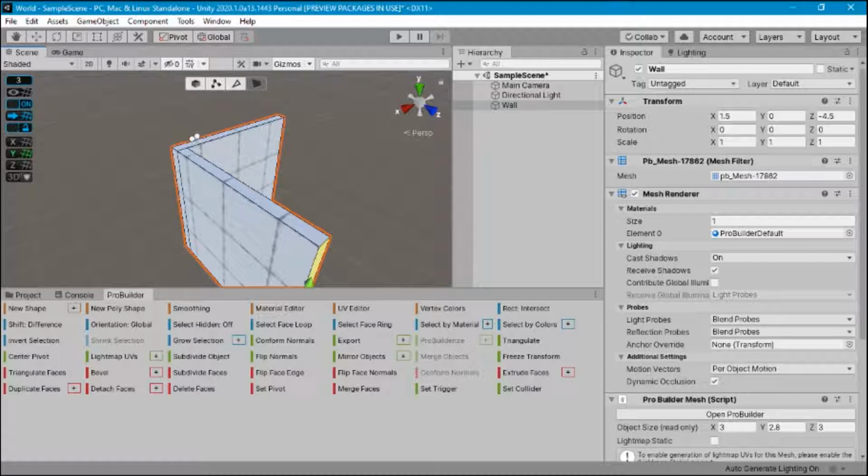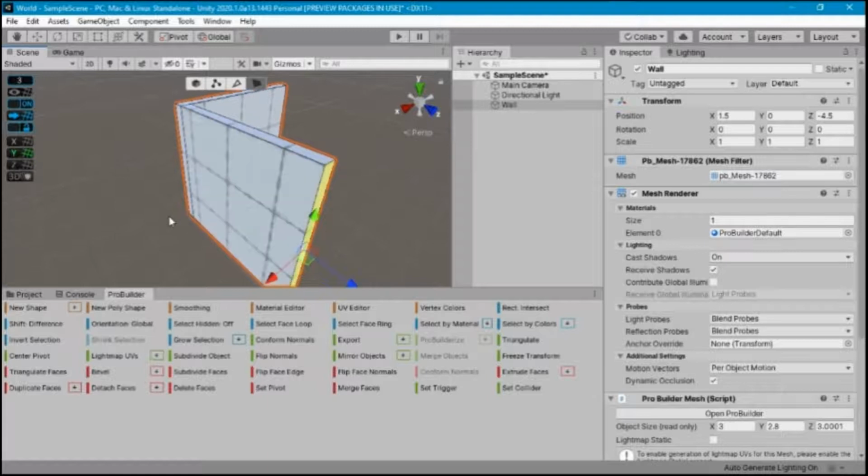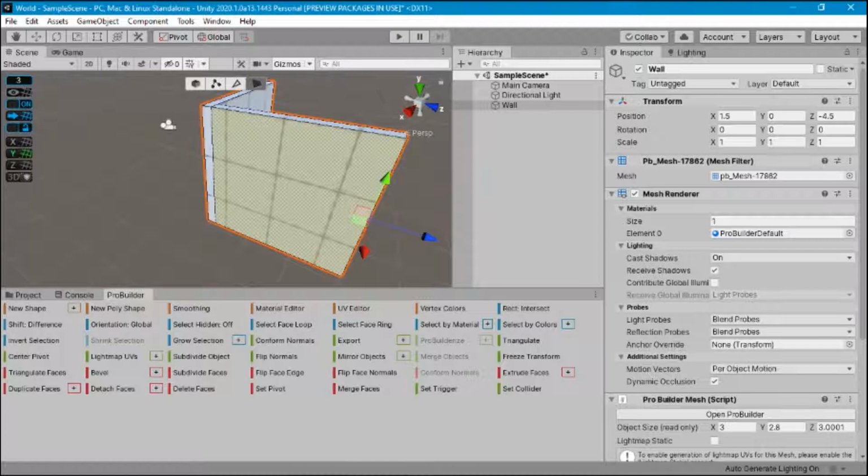Another important detail we should be careful about is the number of polygons on our scenes. In 3D modeling, when people speak about polygons, they actually mean triangles. Fewer triangles mean better performance. We'll try to reduce the number of triangles in our models. Rectangles are made of 2 triangles. If you pay attention to the left face, you will notice it's made of 2 rectangles, which means 4 triangles. But if we merge both rectangles into one, we could get rid of 2 triangles. Doesn't sound like much, but once you start adding tiles to your scene, the numbers can grow really fast.